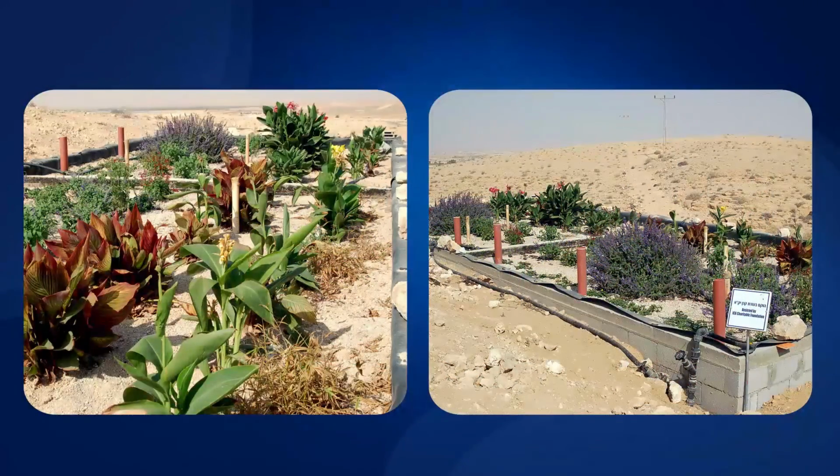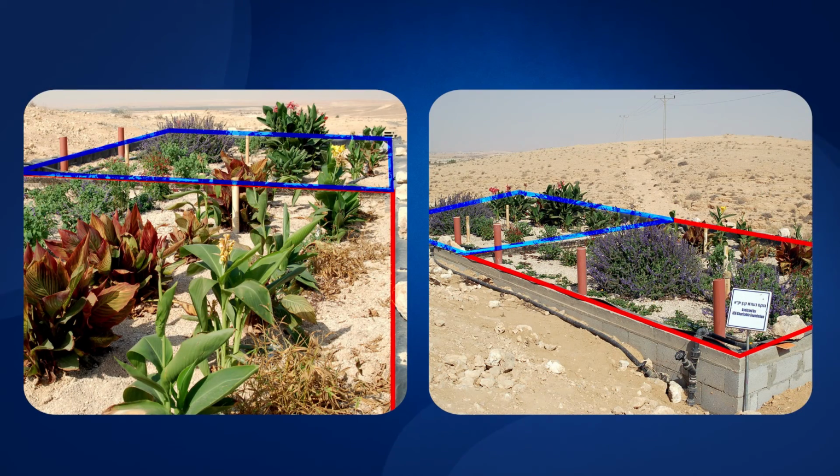It can be seen that the wetland is divided into 2 beds, or compartments. Each bed operates for several days, after which the water is diverted to the other bed. The resting bed is better aerated during this period, and absorbed compounds are further degraded. This staggered operation significantly enhances the system's efficiency.